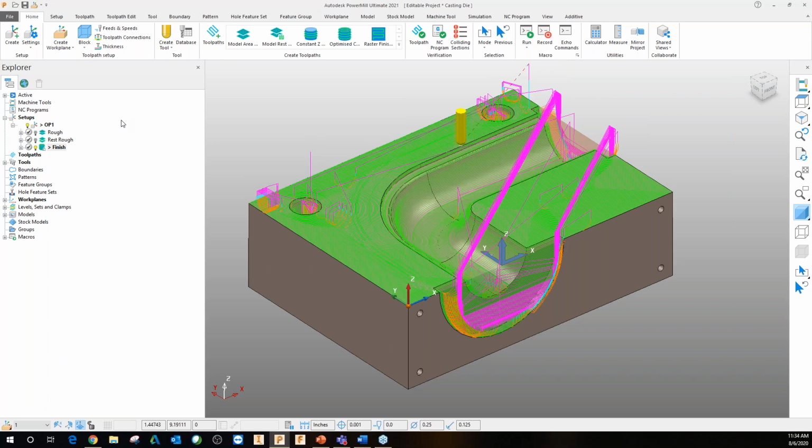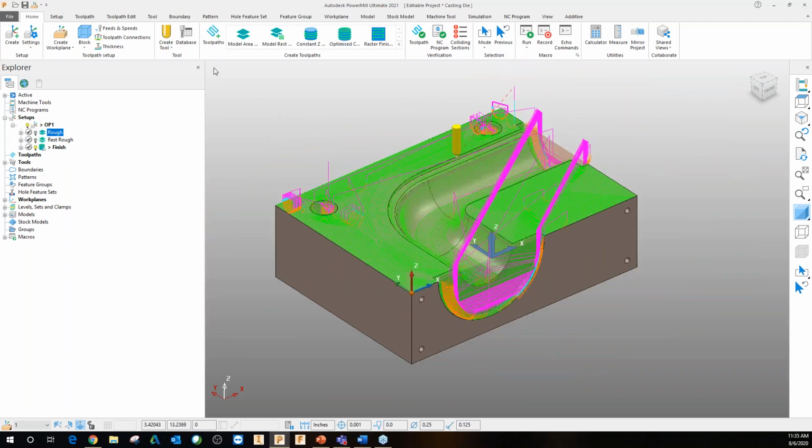You'll also notice with this, you get the ability to do that automatic verification. So it automatically generates these toolpaths, but it also verified that there aren't any collisions. So I get toolpaths that are ready to run without actually clicking any buttons, but also I know that they're going to be safe to run on my machine. So you kind of get the full range there, start to finish. It's going to be efficient, but also safe.